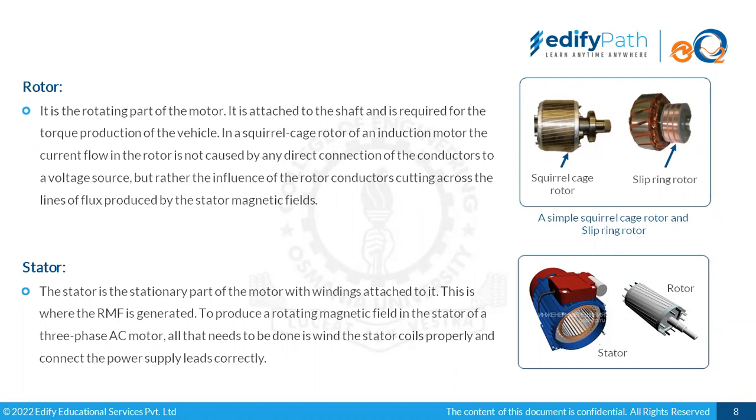If you see this picture of this motor, you could see a capacitor on it. The presence of the capacitor shows that the motor is a single phase motor. Normally single phase induction motors are not self-starting, so we use a capacitor to make them self-starting. This is the concept we normally see in our home electrical appliances like fans, where we are using a single phase induction motor.